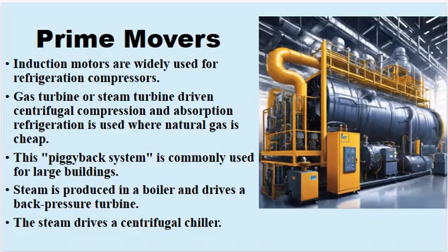These systems utilize gas turbines or steam turbines to power centrifugal compressors, especially in applications where natural gas is readily available and cost-effective. Turbine-driven systems are often the go-to choice for larger-scale refrigeration needs due to their high performance and efficiency. Now, let's talk about the piggyback system.